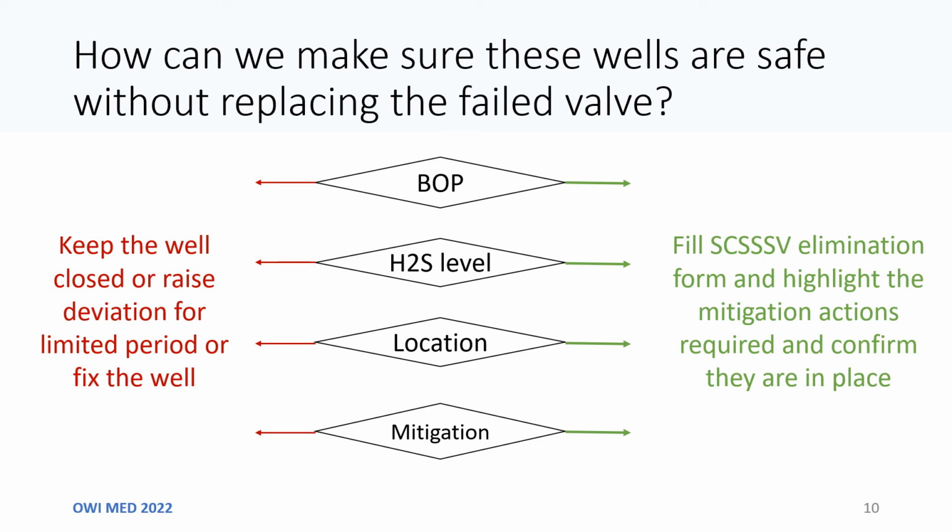The safe distance that we got from the dispersion modeling was then multiplied by a safety factor, and the resulting safe distance was plotted on the field map around the major roads, the major facilities, and the camp. Any well located in the area around facilities, camps, or roads was excluded for proximity to active locations.